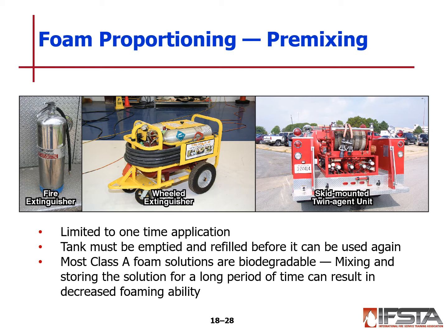If you're carrying onboard foam proportioners that inject, which a lot of people are carrying for Class A foams now, that solution is stored in that tank, but again, it is biodegradable. After so much time, that foam is not going to generate the percentage of foam that we might be looking for. So we have to keep that rotated. In tank mixing or batch mixing of foam, we have to clean the tank out after we're finished using it.